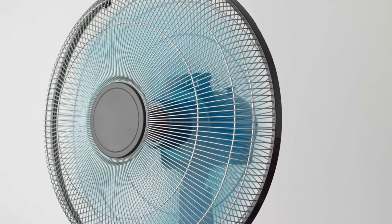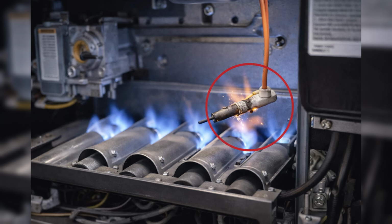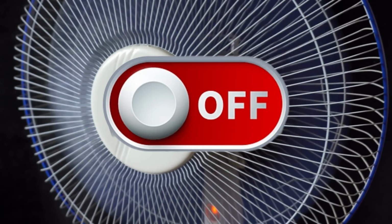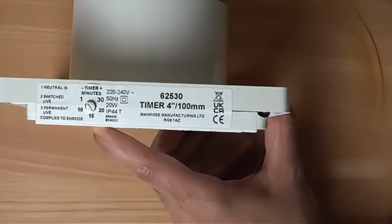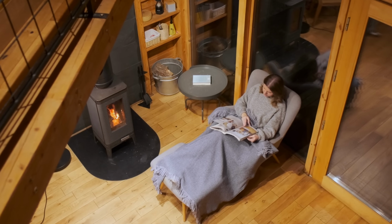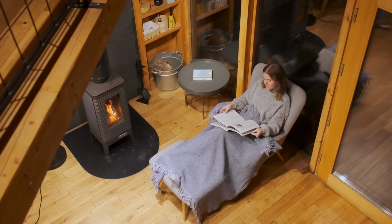There is one final value that most people miss, and it is the fan-off delay. When the flame in your furnace goes out, there is still about $5 worth of free heat sitting in the metal heat exchanger and the primary ductwork. Standard settings shut the fan off almost immediately. By changing the fan-off delay to 90 or 120 seconds, you are harvesting that residual heat and pushing it into your living room. You have already paid for that energy. You might as well use it.